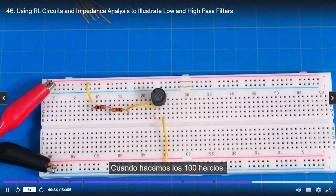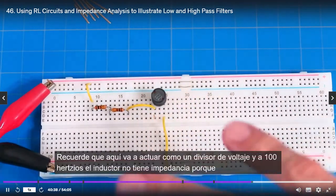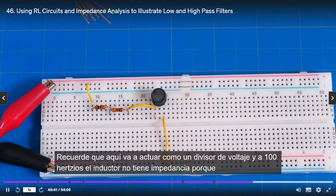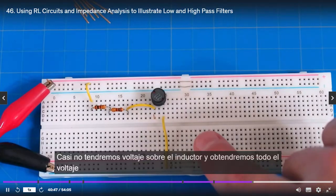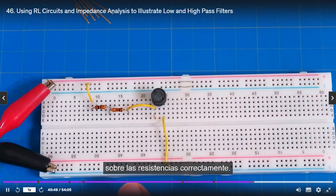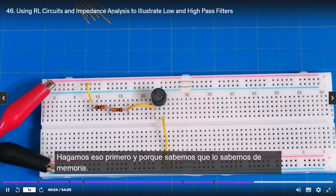When we do the 100 hertz, remember this is going to act like a voltage divider. At 100 hertz, the inductor has almost no impedance. Because of that, we're going to get almost no voltage over the inductor, and we're going to get all the voltage over the resistors. So let's do that first, because we know that one from memory.